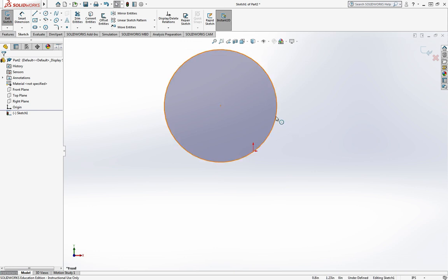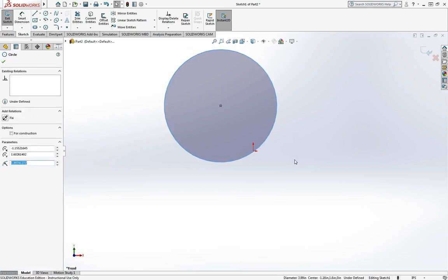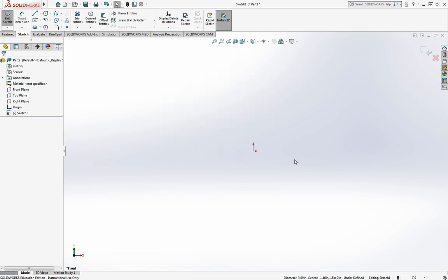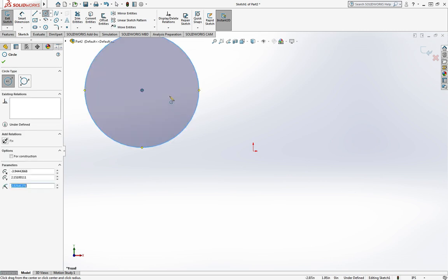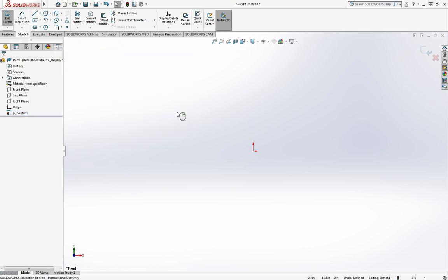What you have to do is select the edge, then hit the delete key above the arrow keys, not the backspace key, not the delete key over by the number pad, but the delete key above the arrow keys, and then it'll disappear. It doesn't work if you don't hit the right delete key, it won't go anywhere. Alright, you can see how you can do that, right?